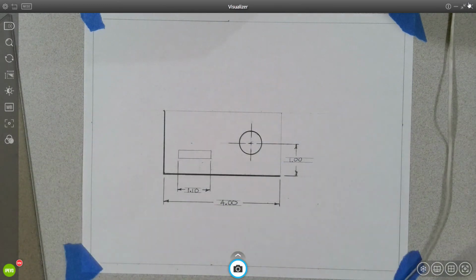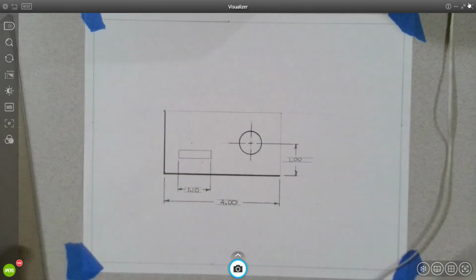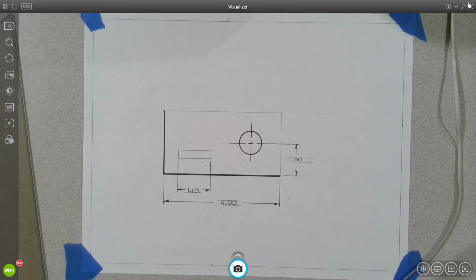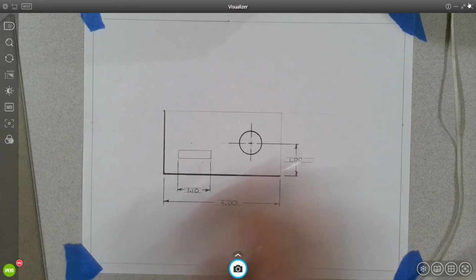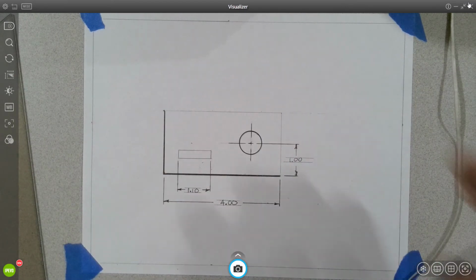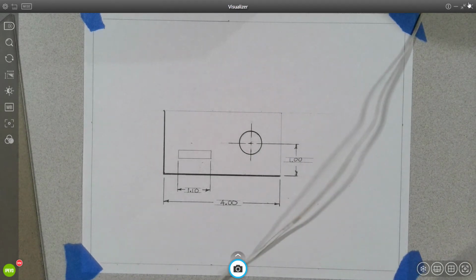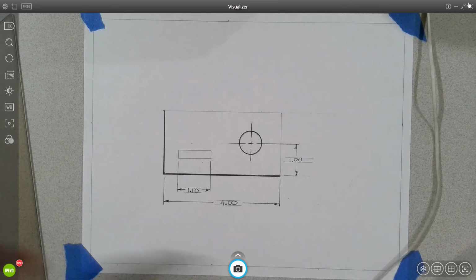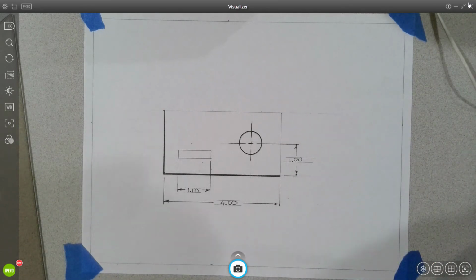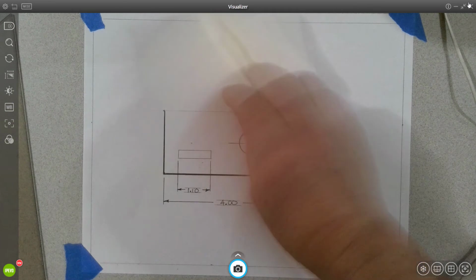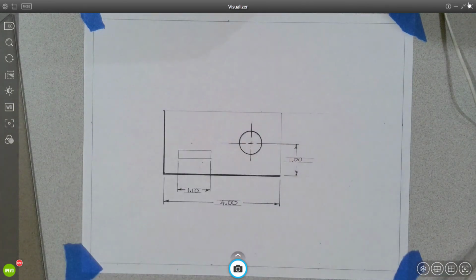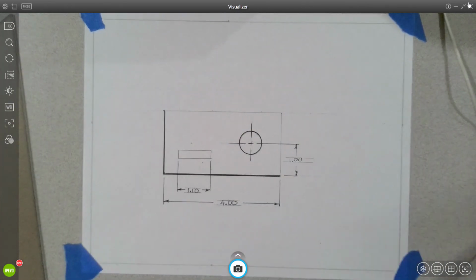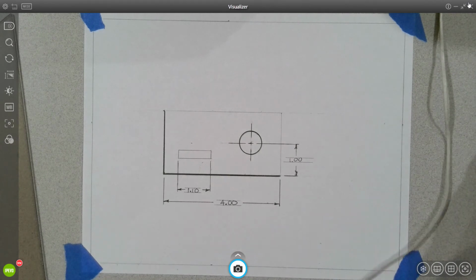As you do it, you're going to get more graphite and more graphite on your drawing. Don't wipe it. You're just going to smear your graphite, right? Don't blow on it. You're just going to spit on your drawing. What works well is a towel. You can use a paper towel if you want, and just kind of go like that. It will get dirty, but it'll stay fairly clean.